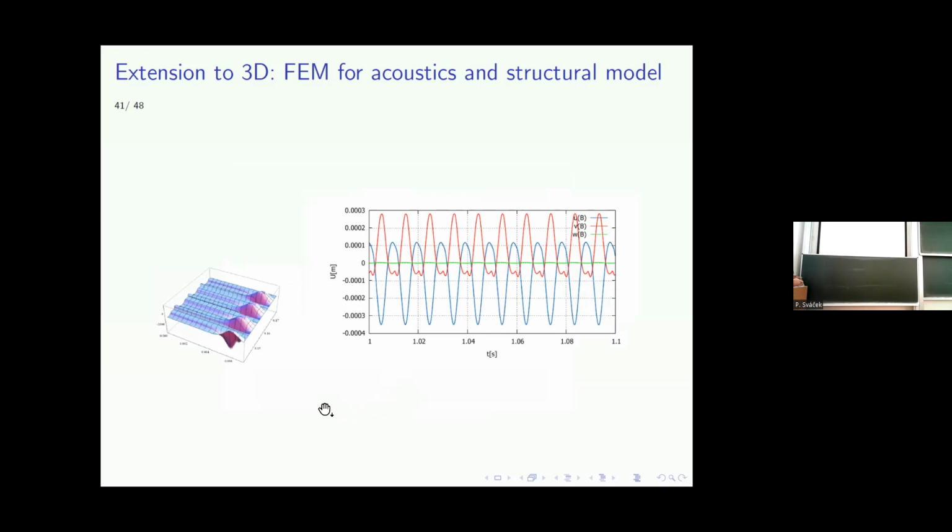The last thing he did was the fluid-structure interaction, where we considered the previously mentioned simplified 1D model of potential flow, and from this 1D model of potential flow we took the pressures and applied them on the structure. And we obtain vibration. These are vibrations in terms of the U, V, and W displacements, which are the X, Y, and Z components of the displacements.